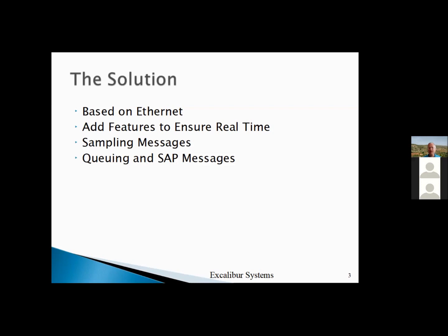It doesn't mean it has to get there in a microsecond. If you need it in 10 milliseconds, it always has to get there within 10 milliseconds. As opposed to Ethernet, where you'll complain one day that the Ethernet is slow, and you'll be right, that can't happen on an airplane. It's got to be the same every day.